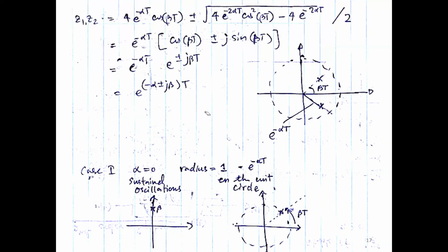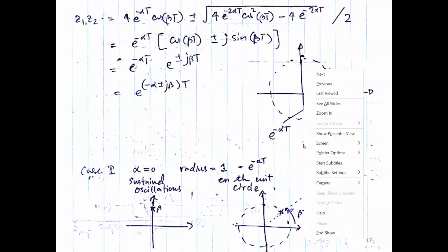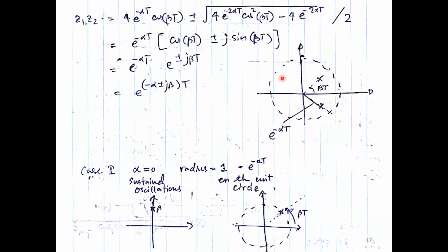All right. Now we have a pretty good understanding about the discrete time poles, right? So if you get something like this, you're good. You're good in the sense you are not too close to the unit circle. Look at here. You are well within, so that is a good sign. You have the fast converging system. We prefer that. And also inside the unit circle, so the system is stable, also good.